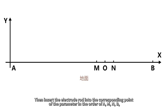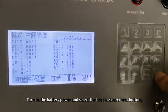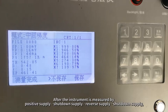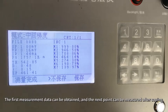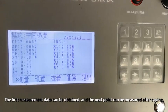Then insert the electrode rods into the corresponding points of the parameters in the order of A, M and B. Turn on the battery power and select the host measurement button. After the instrument is measured by positive supply, shut down supply, reverse supply, shut down supply, the first measurement data can be obtained, and the next point can be measured after saving.